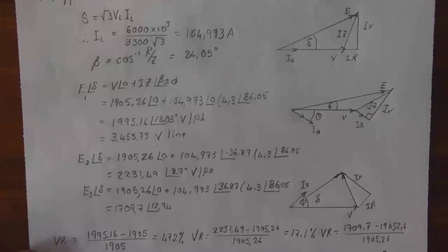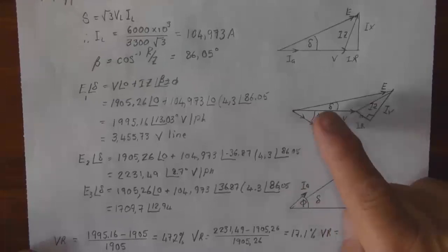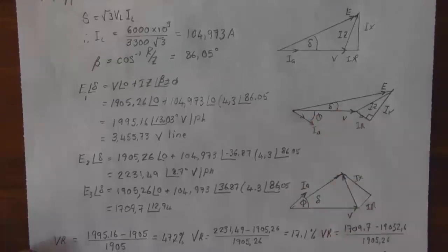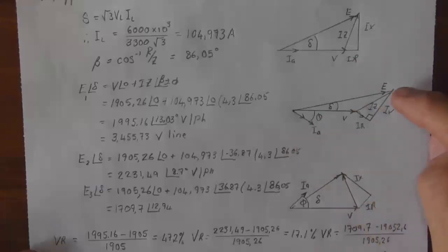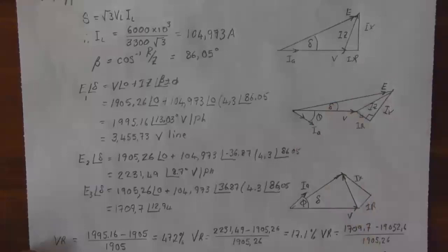Just remember, IR is always in phase with the current that causes it. IX is perpendicular to that current, and where they join, we get IZs, and therefore from the origin up to that point is the induced EMF, and that is the load angle and the power factor angle.